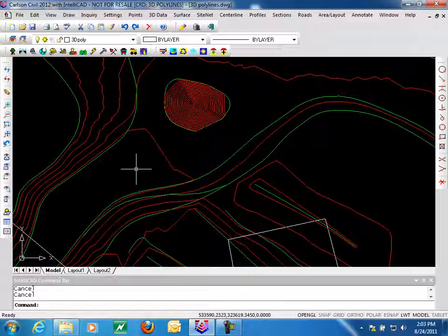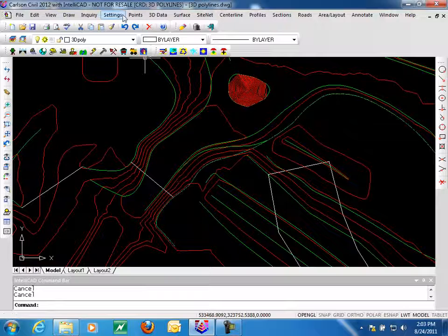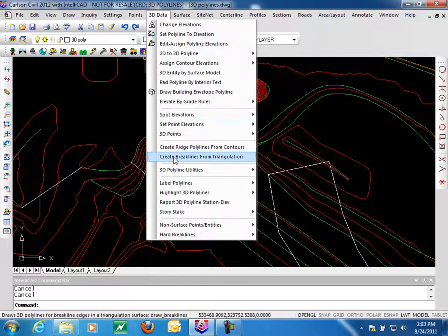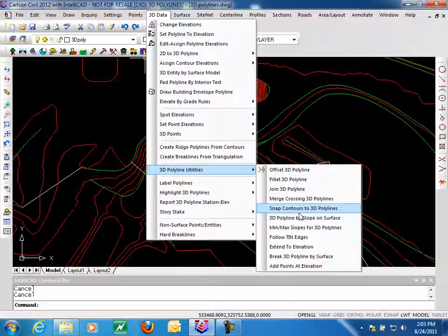So I now have a route up the hill. I can use this to overlay a center line on, to design a road to get me from the bottom to the top of the hill without exceeding a design slope. Okay, that's a wonderful little utility, helpful for designing things like haul roads and access roads.